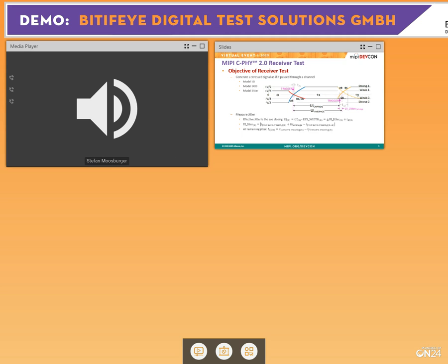Basically that all depends on how the rising and falling edges are delayed or not delayed when going back and forth. And therefore, we are generating what we call the effective jitter, which is the combination of all those kinds of jitter sources combined, which close the inner eye opening, which then makes it difficult for the receiver to receive the signals.